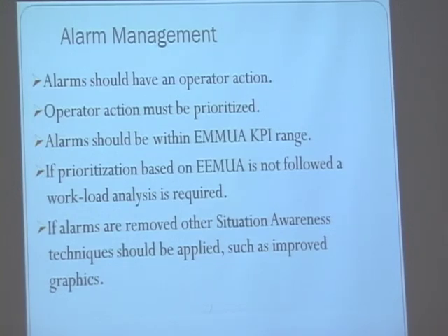So if we're going to reduce those alarms, we've got to think about how we bring back situation awareness through graphics and trending. And today, we've seen very little use of trending. That's not a good thing, because trending was a great situation awareness tool.